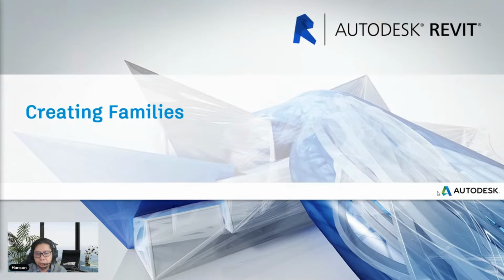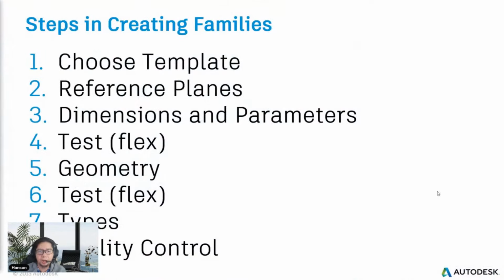Okay, let's do creating families. I have some steps here that you can just screenshot if you like. We'll be using these steps in our creation. Number one is choose template. Number two is reference planes. Number three is dimensions and parameters.